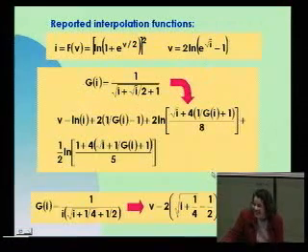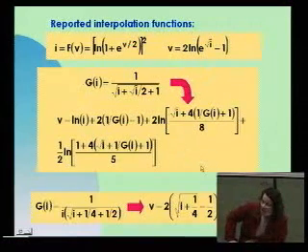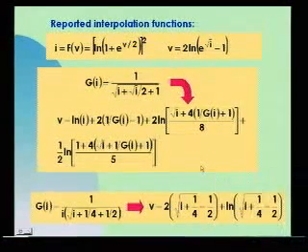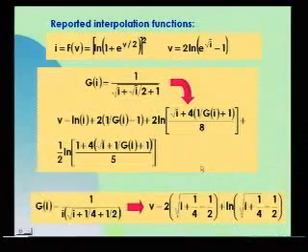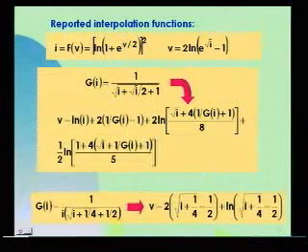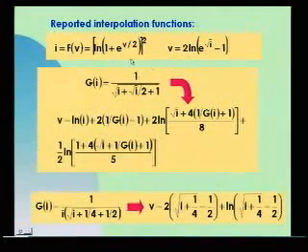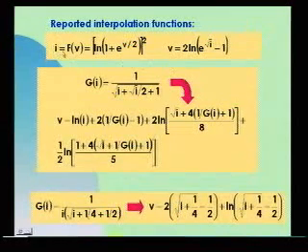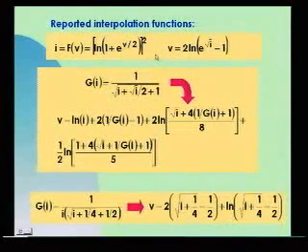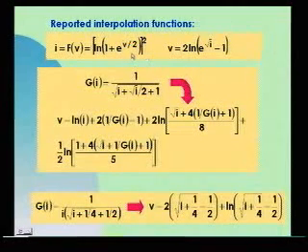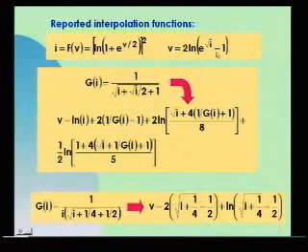No questions. Well, then the EKV people reported these three interpolation functions till now. This first one is directly for the relationship between current and voltage, and is not very accurate, but it has the advantage of being invertible. I can have either I as a function of V or V as a function of I.